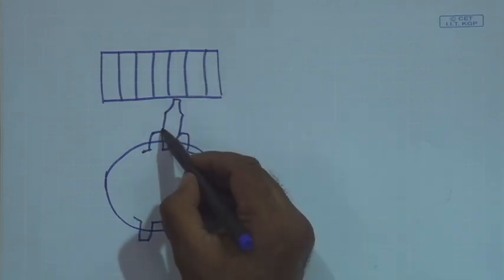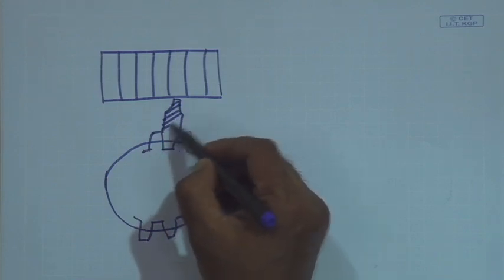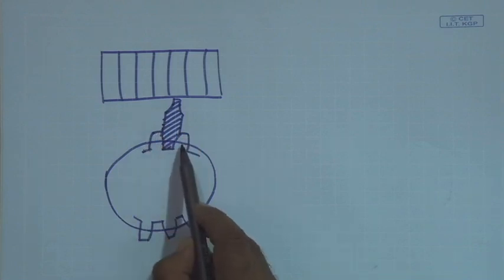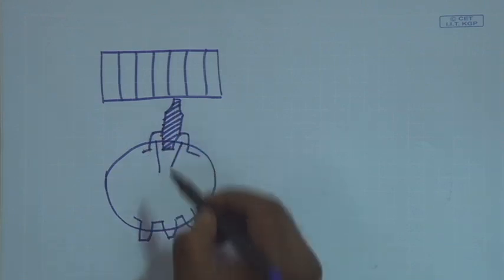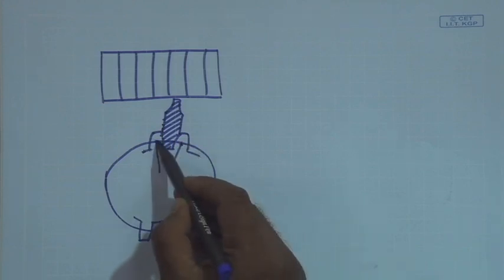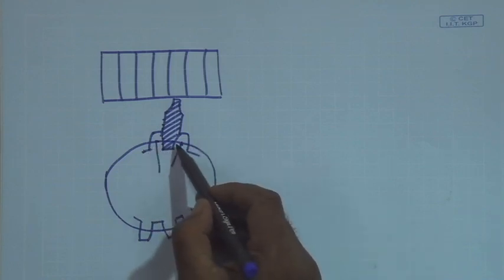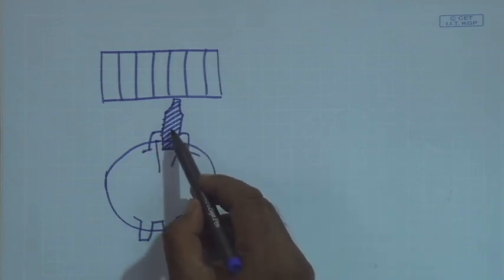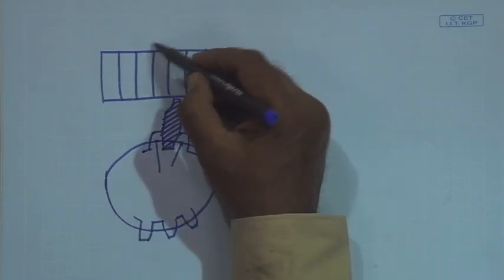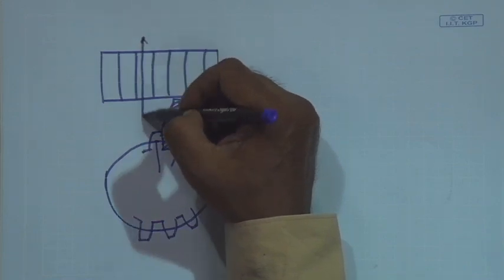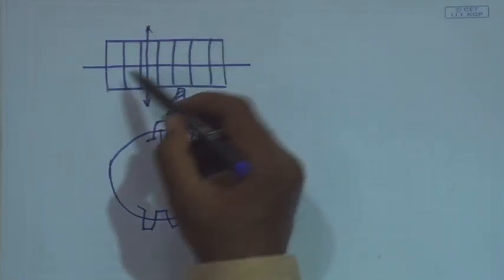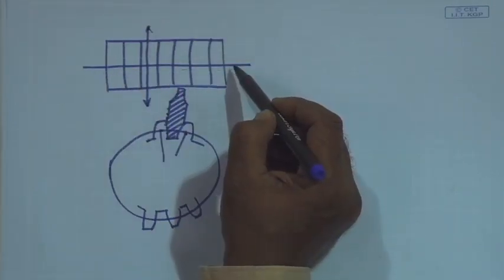The cutter is a physically defined piece, and therefore, it gets defined by this particular gap, and as we have studied previously, this distance is equal to pi into m. So, the cutter is having inside it this particular information, and this information is imprinted perpendicular to the axis.